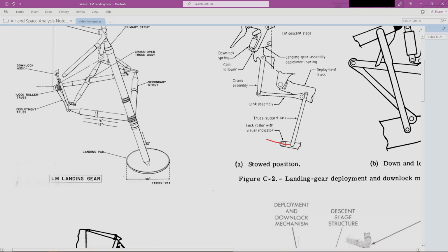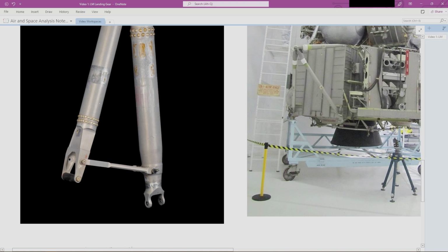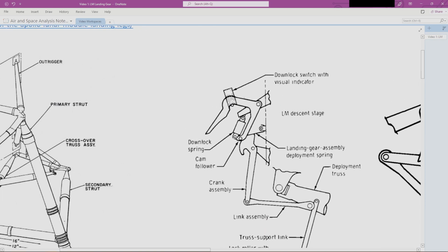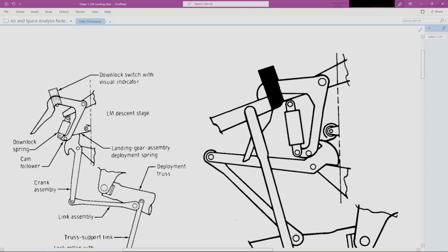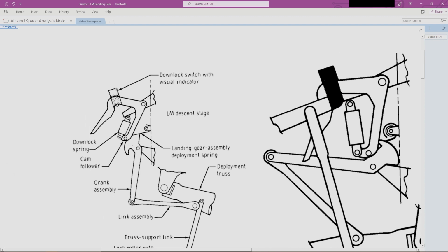Anyways, hopefully I'm not being too long-winded here, but essentially my point before we digressed was that there is a roller and a big hole here, and you can see there's this claw looking piece, and this is the roller right here, and now the claw piece has gone through the roller, and the way that works is it's actually linked to this same crank. You can see there's this surface right here, and then it drops.